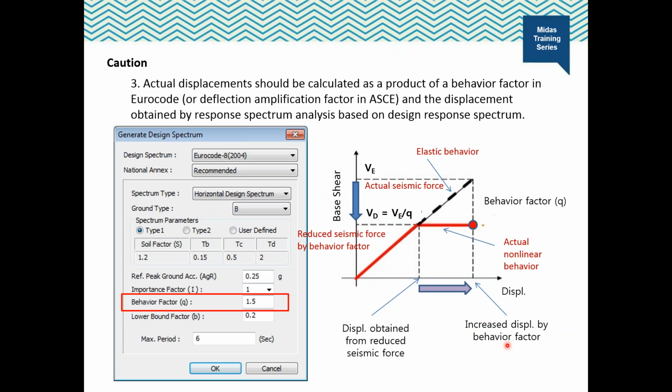To avoid complex inelastic structural analysis in design, the capacity of structure to dissipate energy through mainly ductile behavior of its elements is taken into account by performing an elastic analysis based on a response spectrum reduced with respect to the elastic one. This is called design spectrum.